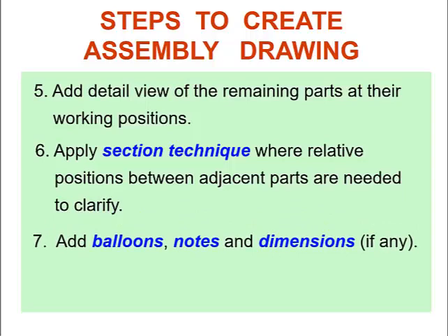Seventh, add balloons, notes, and dimensions if you need them. And eighth, create the BOM, bill of material, a table that has the part names, material, and quantity. You have to create the table on top of your title block.